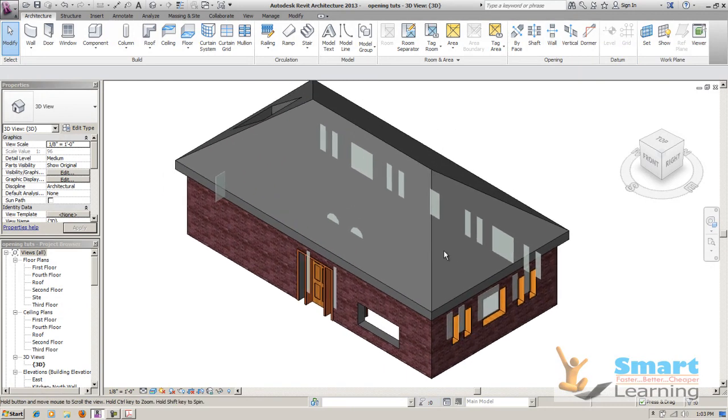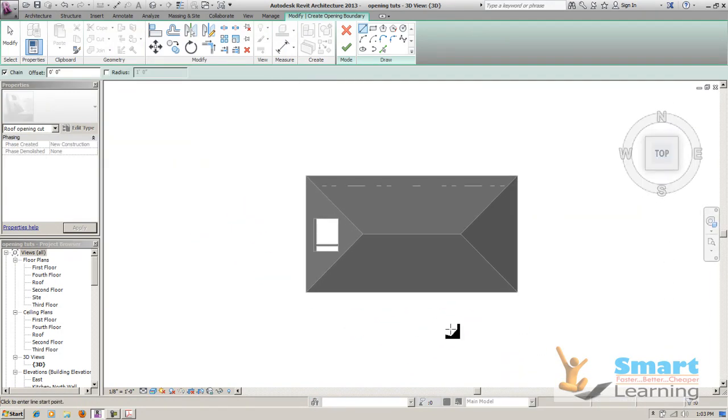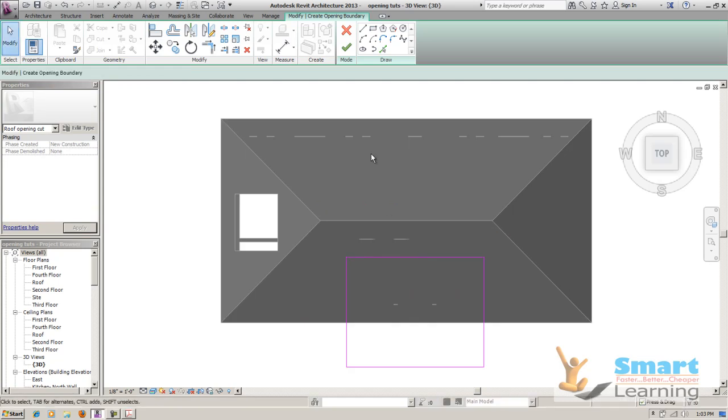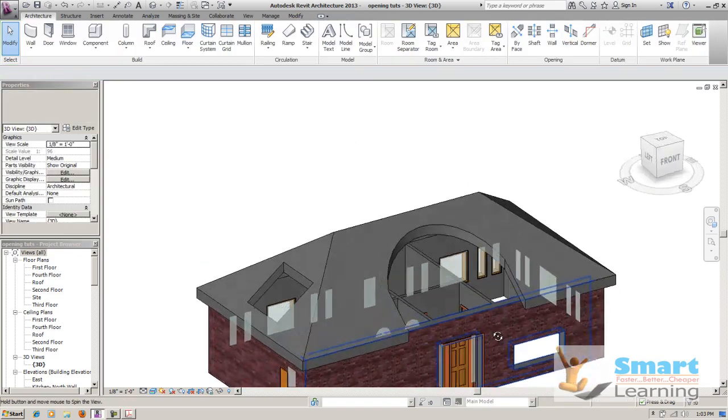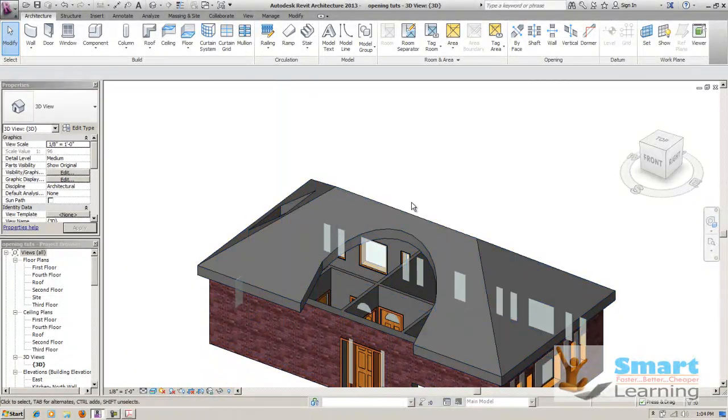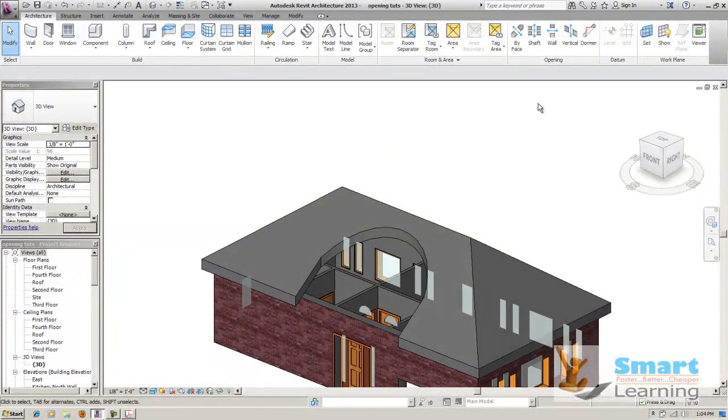Just like that, you can have the verticals. In case of verticals, you can create vertical openings. That means if you go to the verticals and I need to have a special cutout here, select the roof, and I'll go to the top view and roughly sketch the opening. This may be something like this. I'll create 3 points, here 1 point, and the shape I want to give is like this. I'll delete this line and do a little bit of fixing work so that I can have my closed boundaries. I'll go for OK, and now you can see this is the opening which I have created, and here you can have your specific structural preview and dome or whatever you need to do. So with the vertical you can do a cutout like this.